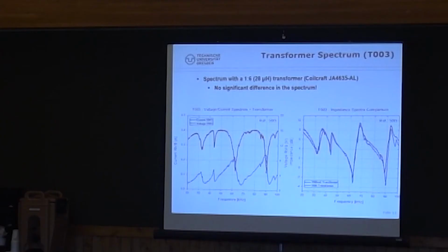Huge. We have a 6 to 1 turn ratio, and although we saw that the voltage this time is not maintained, there was a collapse of the voltage at the resonance because our amplifier was not made to supply the current in the primary circuit of the transformer. And so we also have a current spectrum which doesn't make sense.